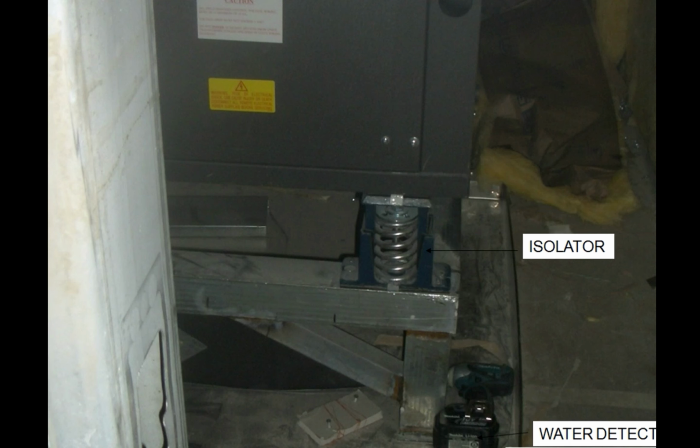Okay, another thing we talk about are isolators. These are basically to deal with any seismic load, shifts in the building, movements, rocking back and forth from things like wind in your structure, so that the equipment itself isn't fixed and doesn't undergo the stresses that the steel structure goes through, to make sure that it continues to operate properly and that it's in alignment with what it needs.